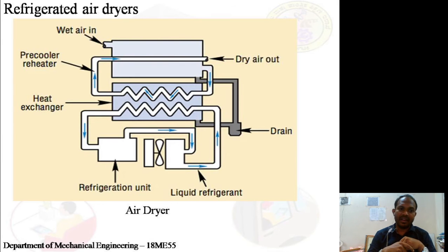So the refrigerated dryers typically generate air with pressure dew points of around 40 Fahrenheit. They tend to be used in general plant operations. They may not be suitable in most cases. Critical processing that demands extremely dry air may not be suitable for this type of refrigerated air dryer, and they are not designed for circuits that see sub-freezing temperatures. Okay, refrigerated dryers are considered fairly economical to purchase and operate.